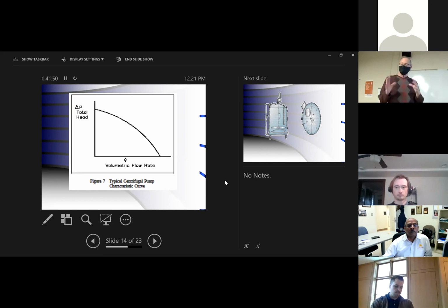You literally could take a centrifugal pump, put a standpipe on it, and start pumping water into it. As you pump water into it, sure it moves, but if you kept adding more and more pipe, you eventually would reach a point where the column of water would be pushing down with sufficient pressure that nothing would flow. It'd just come to a standstill.